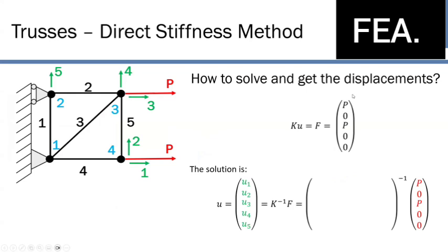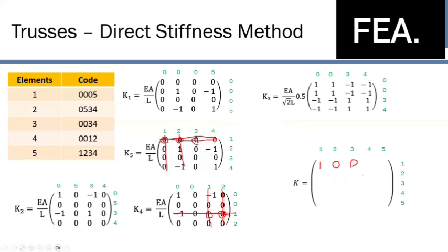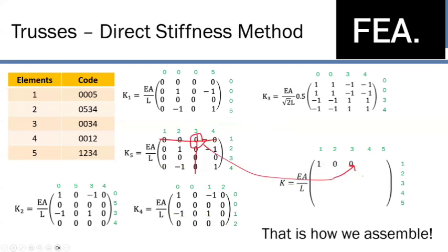Ultimately, in finite element analysis, we prescribe external loading and boundary conditions, and we want to figure out how every single part of this structure moves. We have assigned material properties, dimensions, and some CAD model to represent our structure. We've represented boundary conditions in our own stiffness matrices that are reflective of our pin, our roller, etc.